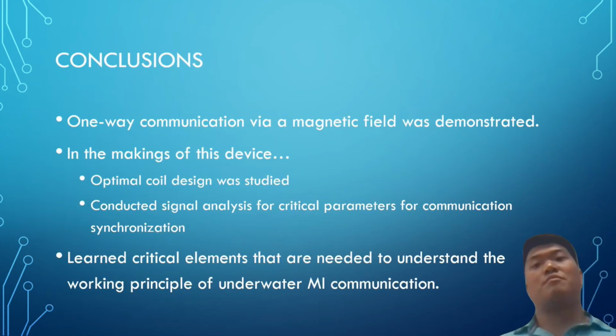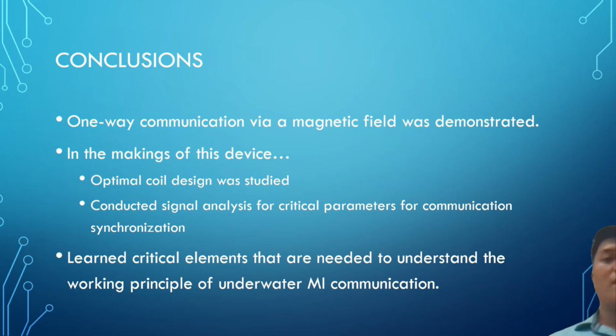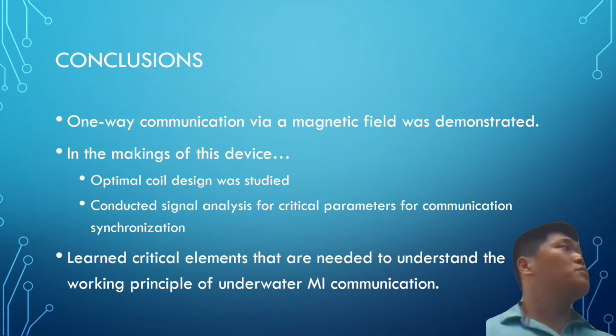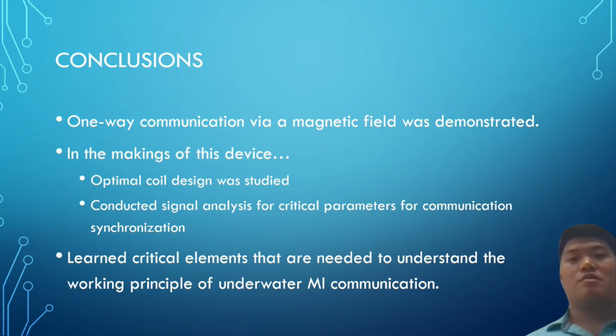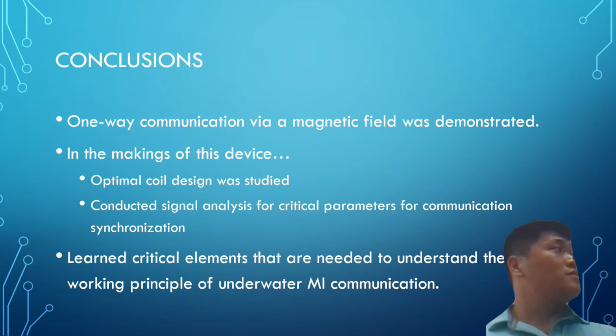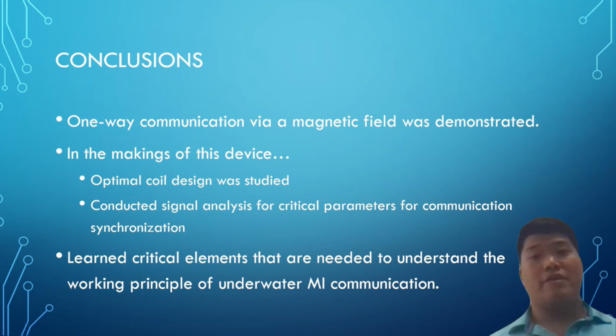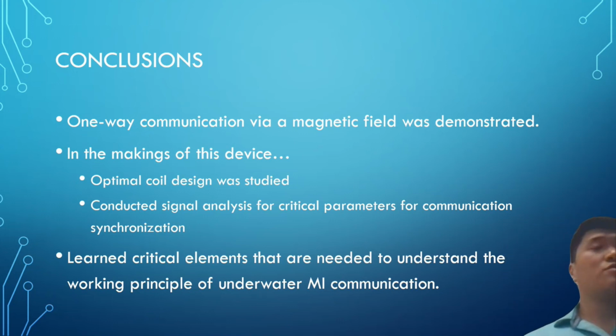So in conclusion, I demonstrated a one-way communication via magnetic field. I studied the optimal design of the coil and conducted numerous signal analyses for critical data in order to achieve communication synchronization. And this project served as a learning block towards understanding the working principle of underwater MI communication, such as the characteristics of electromagnetism, coil design, and communication processes.